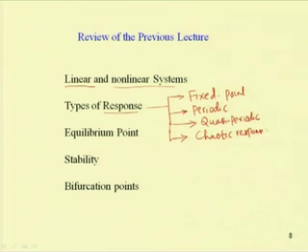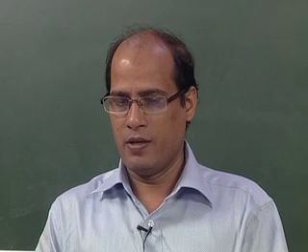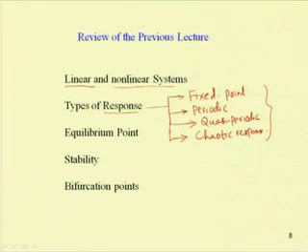We have also discussed the equilibrium points in case of the steady state response. As the steady state response is independent of time, we can find the equilibrium position by putting the time dependent terms equal to 0 and finding the response of the system. So, the response may be fixed point, periodic, quasi periodic and chaotic. In case of periodic response also, the response may be harmonic or other different types of periodic response, but other periodic responses can be reduced to the harmonic response.